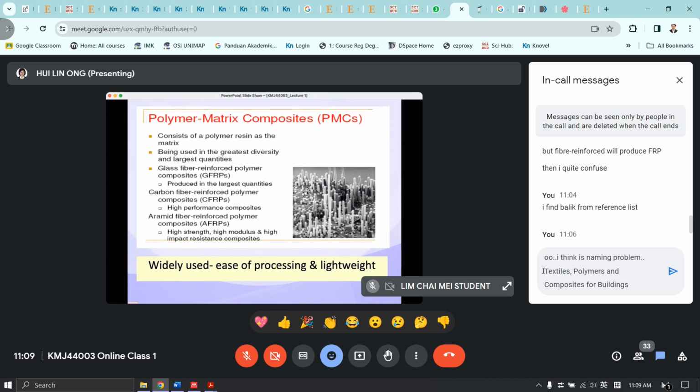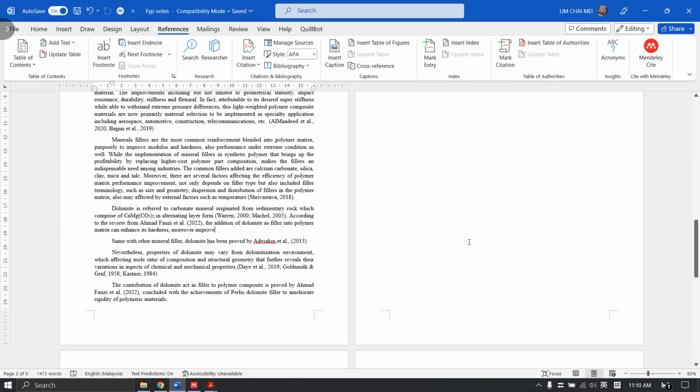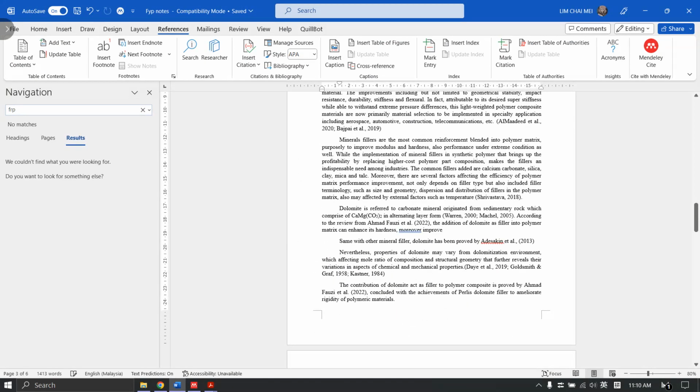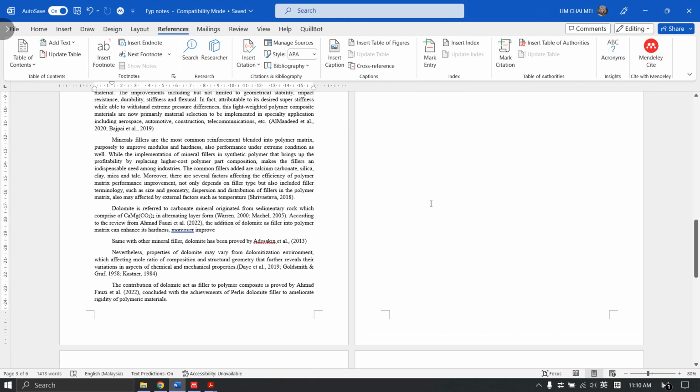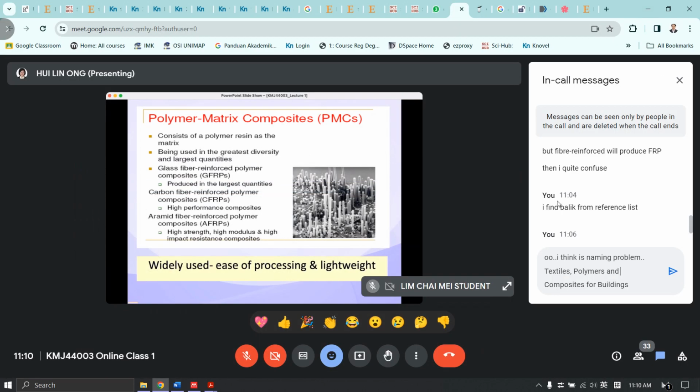So this means it is the weak point, where the failure will start to occur, because the glass fiber is not able to have good adhesion with the matrix. If everything is empty, then it's truly very weak, and we can say this composite is a failure. So we have to do more study and redesign the processing parameters, perhaps, no?